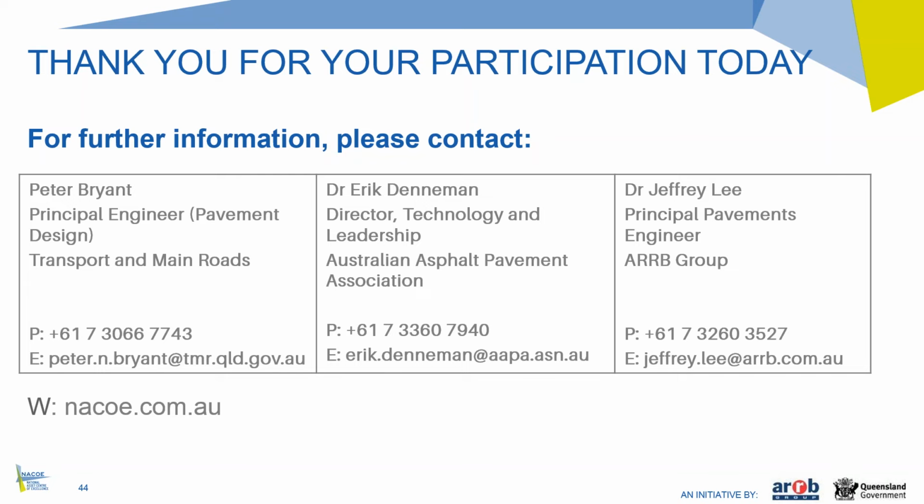Yeah, I can answer that. I think there would be an expectation for the lab to be NATA registered because we require that for any other testing. I don't see why it would be different in this case. The cost of the testing, some rough figures, would probably be in the range of about $20,000 to $25,000 for a single mix. And again, we need to keep in mind the potential savings that can come from optimizing mixes, so that $20,000 to $25,000 is really a very low percentage of a project budget.